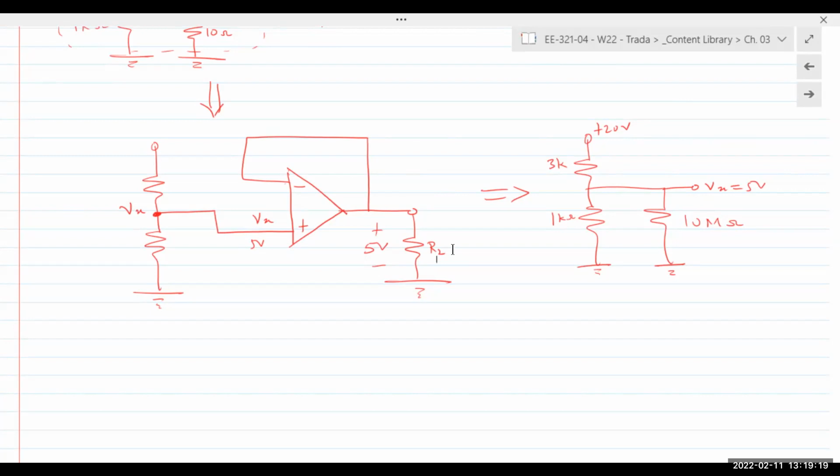Of course, there are a lot of other components that might go into the circuit. There's circuit protection that we need to do, to protect the components from extra current that might surge through. But this is the most basic explanation for why a voltage follower circuit would work as an isolation buffer between the source and your load. Does that make sense?